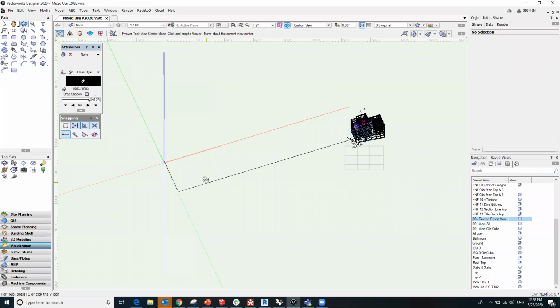I think that's a helpful option, not only because by moving the internal origin, you might create additional obstacles by having to reformat sheets, or, for example, if you're the architect on the project using Vectorworks and your consulting engineers are doing some of the modeling or documentation in Revit, it gives you that flexibility to find a survey point or find a base point in Revit, align the model, and not have to really move the entire project around. So again, shared coordinates in the export dialog, you can gather that point and drop the model in place.